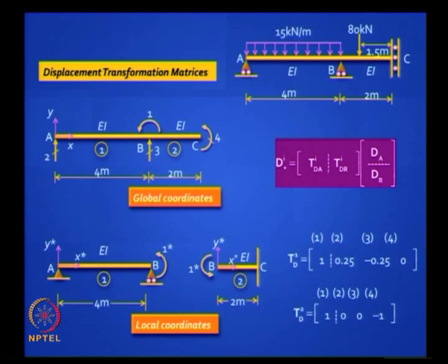That's the only thing. The last one, is it clear? Item number 4, anti-clockwise moment. Here you have to be careful. If you give an anti-clockwise moment here, at the other end you will have an equivalent clockwise opposite moment. So this is the only thing you have to be careful about. Maybe you might like it in the old style.